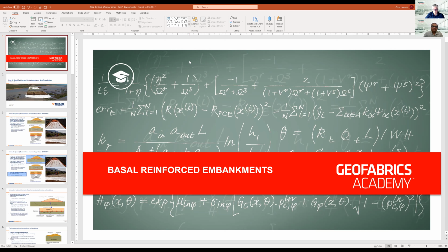That's a pretty slow situation because you're having to wait for the pore pressure to come to the surface and then drain out. But people do put granular material on top of the basal reinforcement, in some cases, so that it acts as a drain above the basal reinforcement. But there it only has to be a fairly clean sand to act as the drainage layer in that particular case.